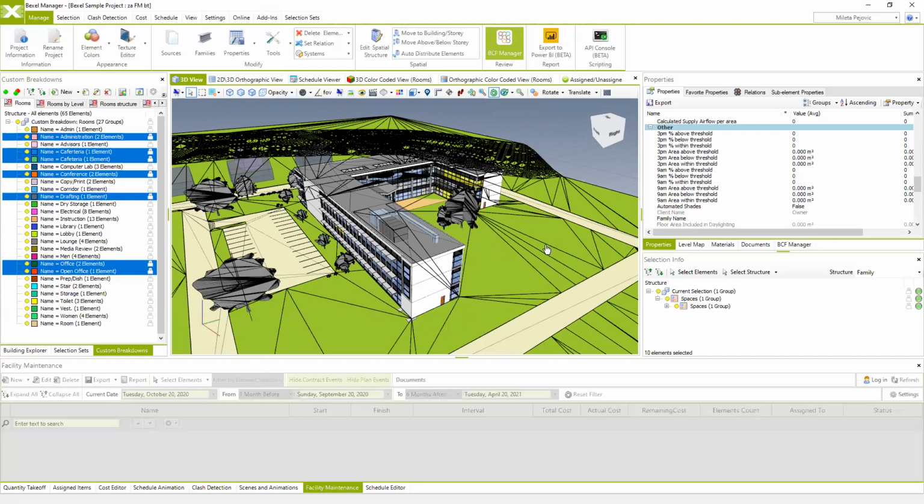So once you confirm that everything is according to the as-built project on site, the next step is to add specific information to your BIM model, which could be valuable and used for next processes, such as facility maintenance information, asset information regarding the, let's say, installed equipment, warranties, all the necessary approvals and documentation which could be saved along with the as-built documents.